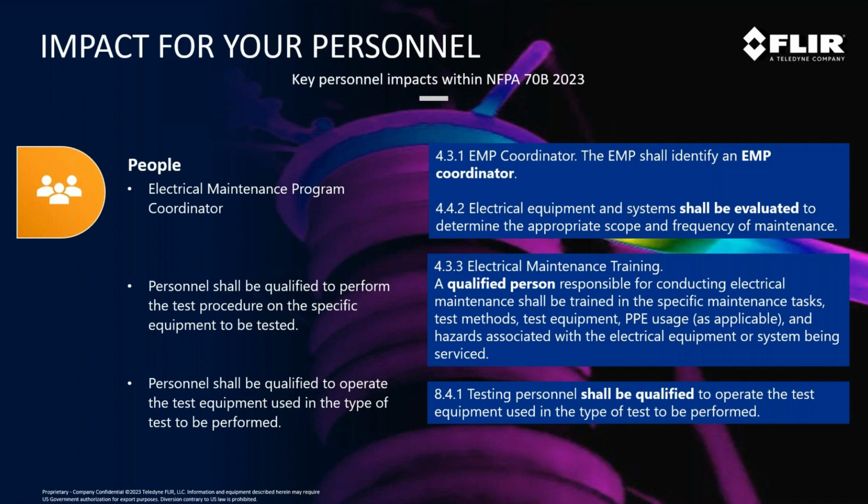So it's not just thermography, but when it comes to qualified, if you need to take temperature differences and capture those through thermography, you need to be qualified to do so. And that typically means that you've gone through at least a level 1 ITC or infrared training certification process so that you are basically validating the fact that you are properly trained in the use of the tool, i.e. the camera, to perform those tests and testing methods.